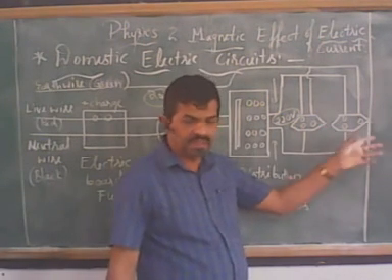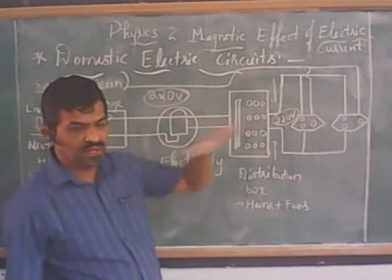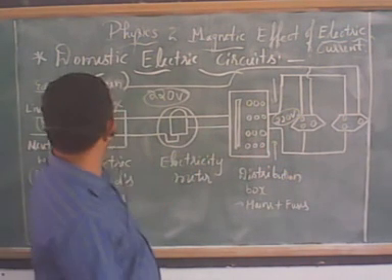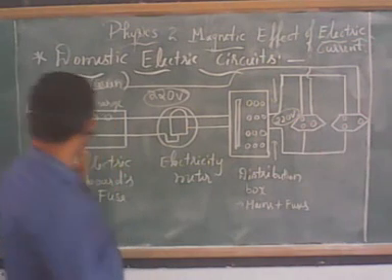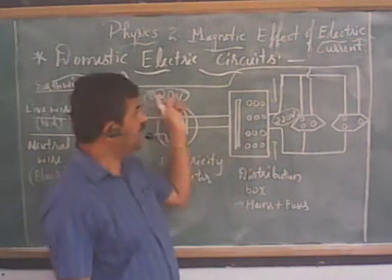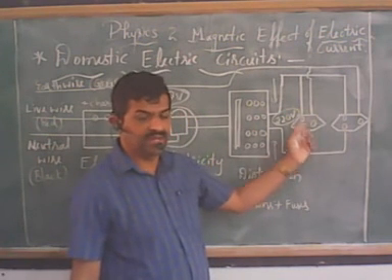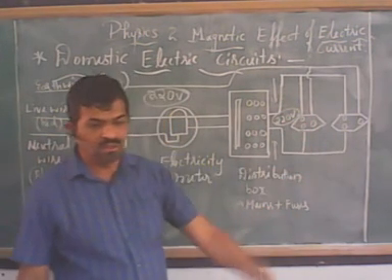The neutral wire passes through the electric board, electric meter, distribution box and various home appliances in the rooms, in the various branches of the electric circuit. And here, lastly, the earth wire does not pass through the electric board, electric meter or distribution box. It is directly connected with all home appliances here. Then it goes directly into the earth.